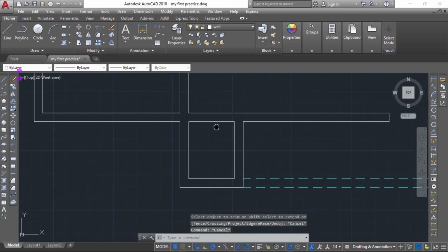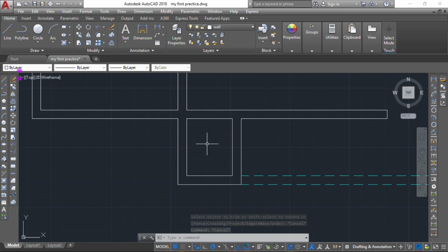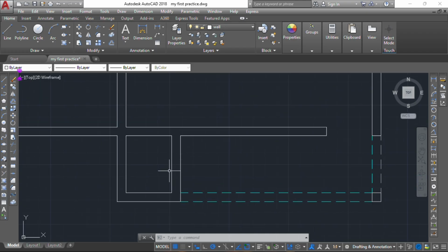And then the last but not the least, which is the visitor's toilet here. Now we can either create our door here opening to the wall here or opening to the wall here, but we cannot leave it outside. We cannot create our door outside here because it is unreasonable. If we are having visitors, we are calling it a visitor's toilet. A visitor does not have to come out of the building to be able to access the toilet here, right? So what we just need to do is fix it either here or here,